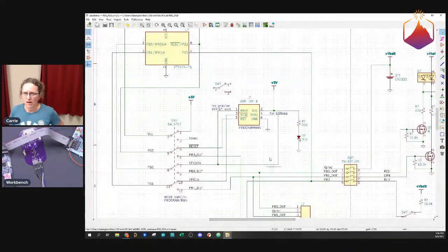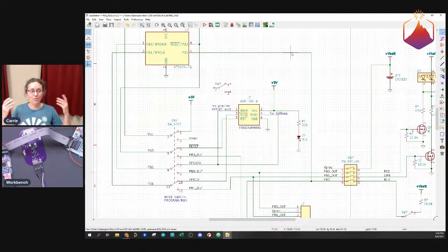Here, what we have going on is our three lines. We only have 3 pins on this processor that we can actually use. All 3 of them go through this switch to be our red, green, and blue control. So every time there's a cycle where red ramps up and blue ramps down, and then red ramps down and green ramps up, that's how it does this rainbow fading. And there are 3 parts to the cycle.